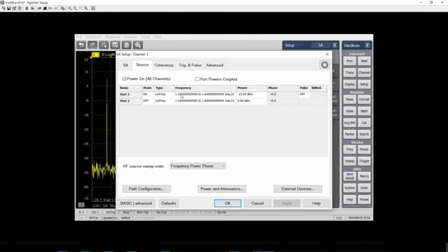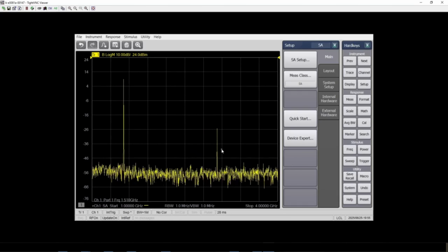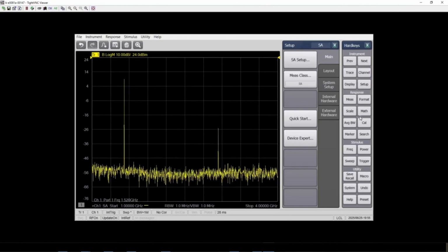And the other one that I want to show you is also the power. If you want to do power, you can do this, and this is where you change the power range. And the last one will be linear frequency and power. So I think this is useful when you want to map out at different frequency, at different power level. It's similar to GCA, gain compression test, but it's not as easy as that. So we have a flexibility there. The point I want to bring out is that we have a flexibility to change whatever sweep that you want. So it's up to you. So it's actually as simple as that.